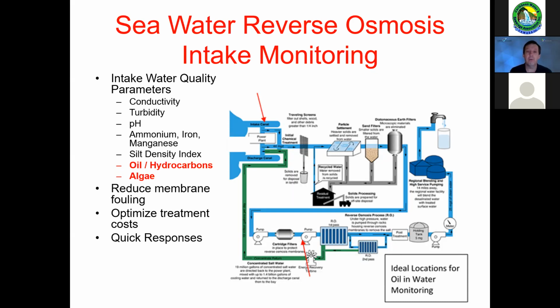Not all fuels and not all hydrocarbons and oil are going to float. Benzene and other monoaromatic hydrocarbons are soluble in water, into the thousands of ppm range in some cases for benzene. And that's very temperature dependent. But if it's soluble in water, it doesn't really matter if it can float or not, or how deep into the water column you're having your intake. It is possible to have benzene and other light hydrocarbons present in the intake, regardless of where you are.